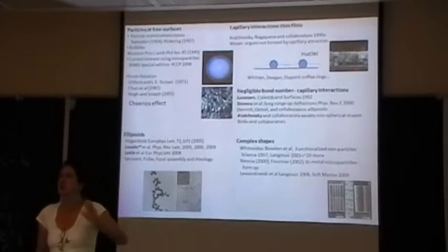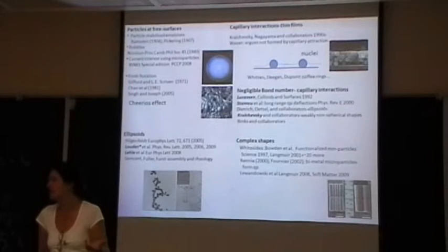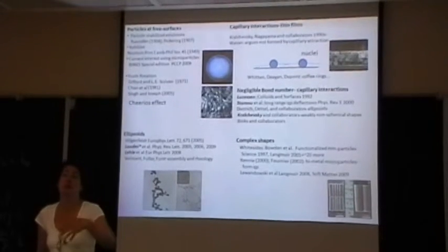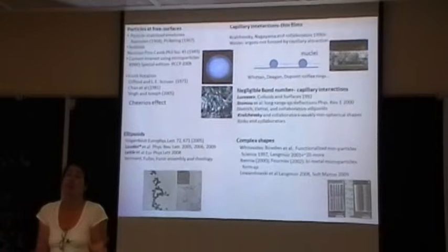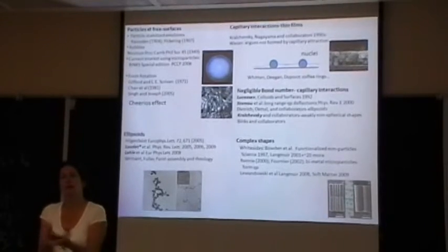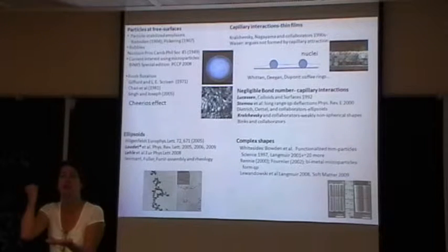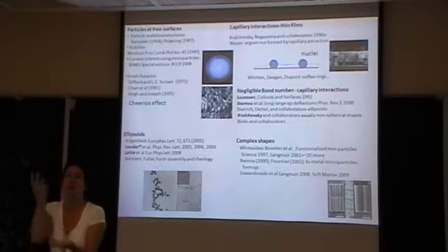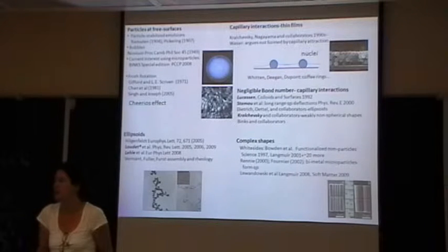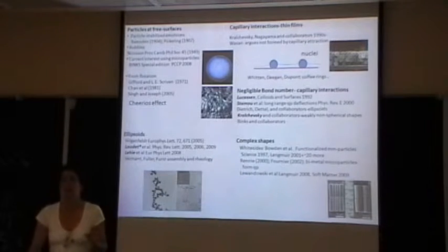Now these crystals are being looked at for applications such as interesting propagation of signals via photonics and other applications. There are also people using them as templates where they want to make, say, a separation membrane with a certain porosity. They'll infill between those particles with some material, and then get rid of the particles by some reaction technique. Often they melt them away or vaporize them away at some temperature. Okay, so there's a lot of interest in forming organized assemblies.